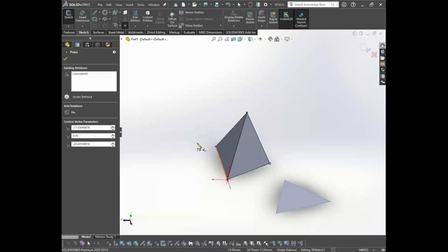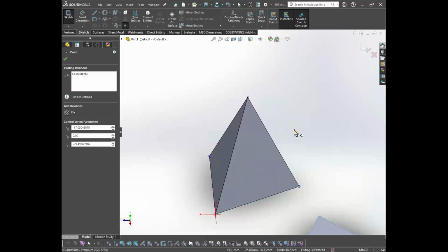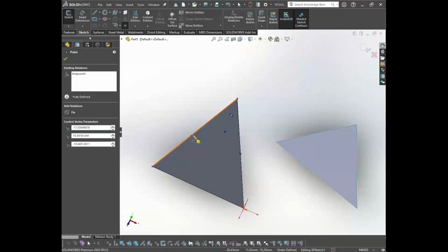This we can consider as the linear differential equation. So in the background, it will solve the linear differential equation. Whatever the deformations are occurring, those always occur at the node locations, and the data from these node locations is considered for the solving purpose. When I turn it to the higher quality element, that is, I increase the power of the differential equation, the solver will introduce more nodes in between.